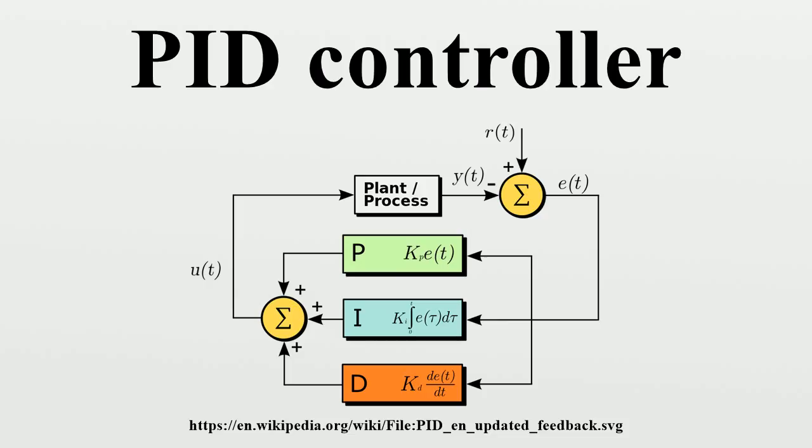In contrast, a small gain results in a small output response to a large input error, and a less responsive or less sensitive controller. If the proportional gain is too low, the control action may be too small when responding to system disturbances. Tuning theory and industrial practice indicate that the proportional term should contribute the bulk of the output change. In a real system, proportional-only control will leave an offset error in the final steady-state condition. Integral action is required to eliminate this error.